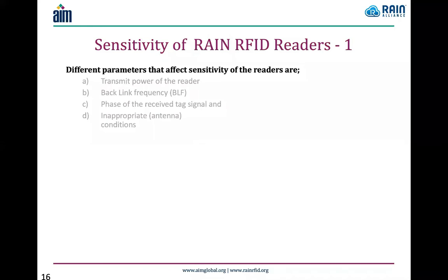But just measuring the receiver sensitivity over the transmit power of the reader may not be enough to determine the overall functionality of the reader. In general, the reader-receiver sensitivity is dependent on design choices, for example the transmit power, the oscillator inside, or the signal interpretation software of the reader. It is to be noted that reader sensitivity is not dependent on the environment of the application itself. The environment may affect the overall system performance, but not the sensitivity of the reader.